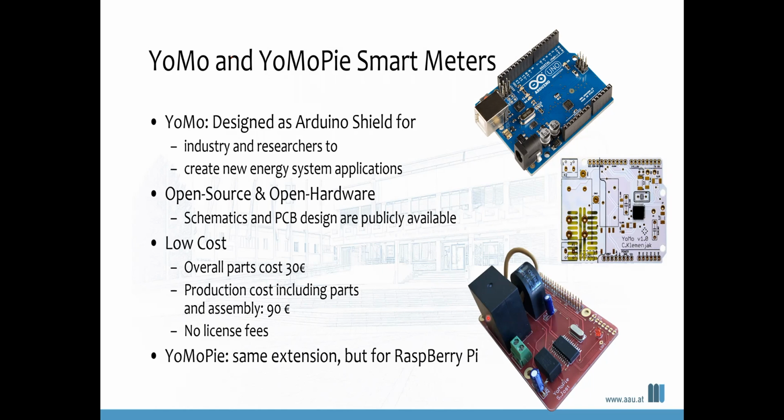But it was a challenge designing this in a proper way. So there is the need, for example, to separate the net voltage part from the electronic part, being sure that nothing goes back to the Arduino. So this is quite some design effort. But once we had it, we provided it with the software and the design documents as open source and open hardware. So the schematics and the PCB design are publicly available.